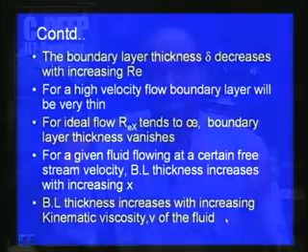So, from this we can finally summarize that, as far as boundary layer formation is concerned, the boundary layer thickness, or how much the boundary layer effects are to be considered, depends upon the kinematic viscosity, upon the shape of the body over which the flow is taking place, and upon the Reynolds number or the fluid flow velocity. Depending upon all these parameters, the nature of the boundary layer changes, and then we have to consider the boundary layer accordingly for various solutions.